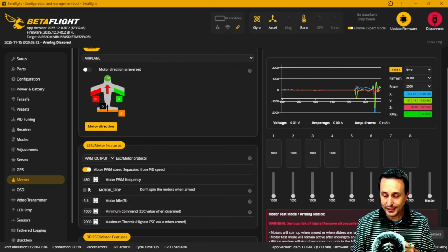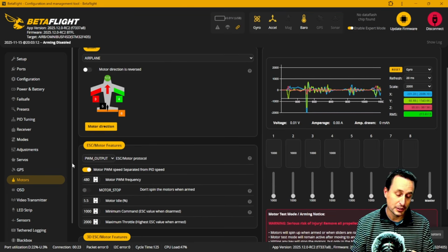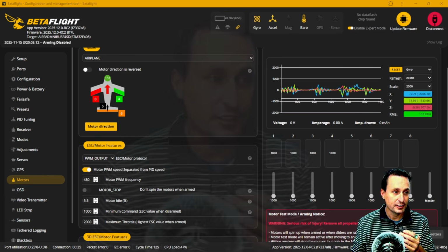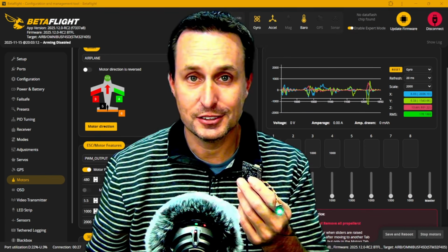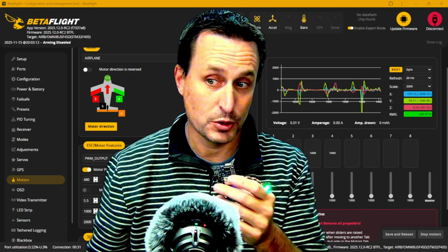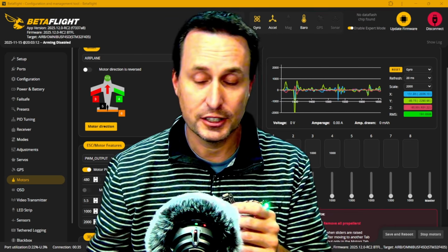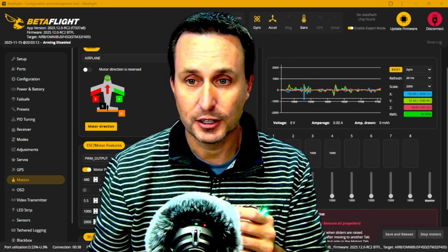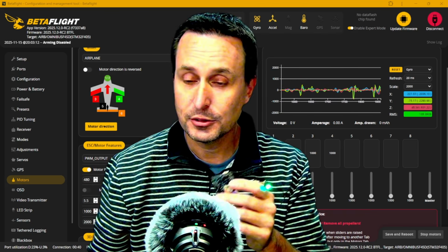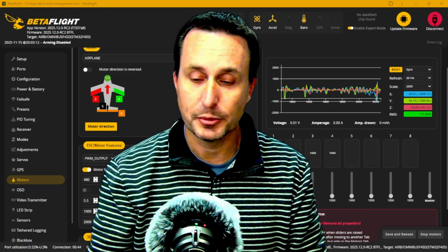I'm going to go ahead and get this all plugged in, and what you will find out when you plug yours in is that your ESCs or your servos aren't going to work. Your ESC should work now, so we're going to put that on motor 1, and when I move the motor slider up, we'll show that in a second, that will work, but the servos won't work. So we're going to have to do some remapping, unfortunately, to make those work. So let's step through that process and what we have to do there.